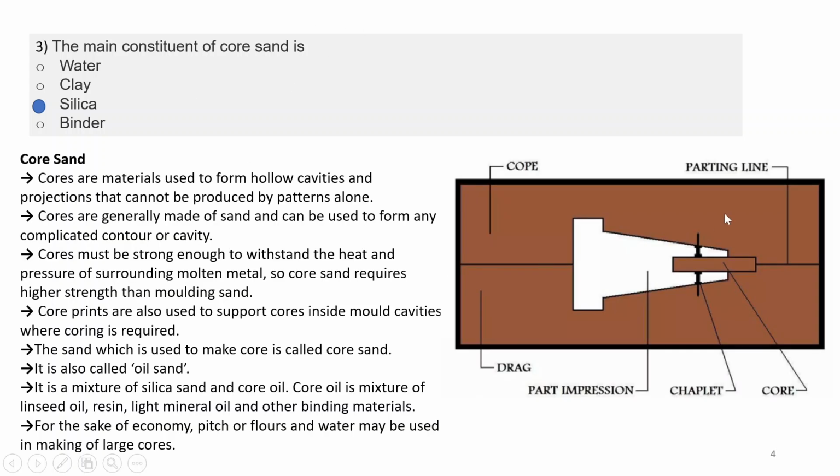Okay, now in this particular casting, you can see this is the core. It is used to make hollow castings. Some part won't be exactly fit. You can entirely fill it and then drill a hole as well, but that will add to your extra work, and also you'll be losing some material.